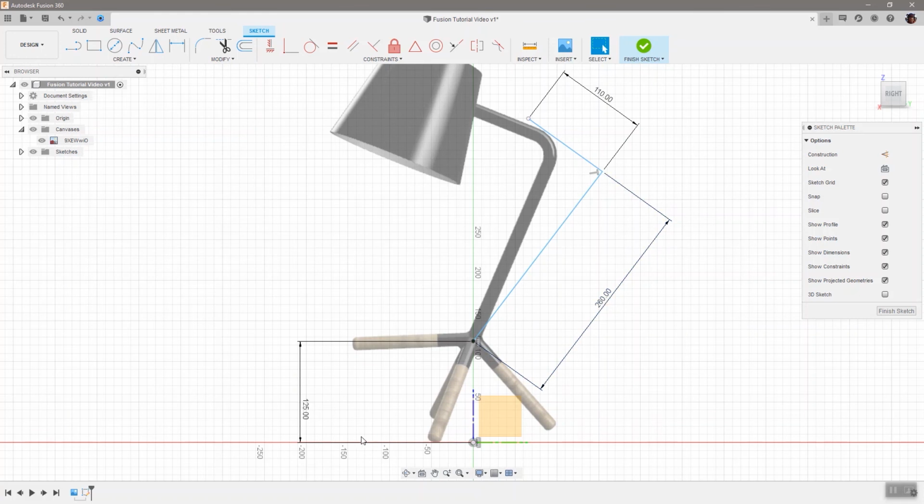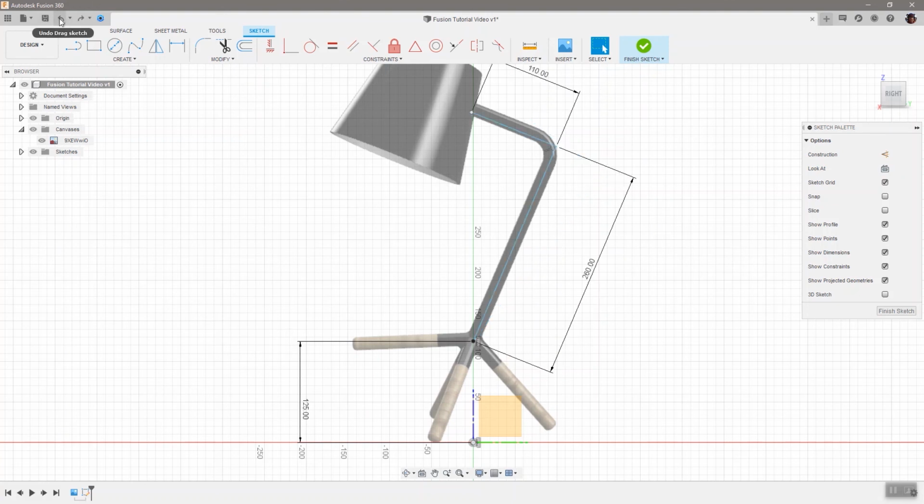It is fully defined. There is nothing saying that your entities in a sketch must remain fully defined in all circumstances, but it is generally considered best practice because it means you thought of everything, and there are some strange situations where in certain cases things can flip around on you. So it's a good idea, at least once you've got a better idea of what you want to do. So let's undo, get myself back to my positioning where I liked it.